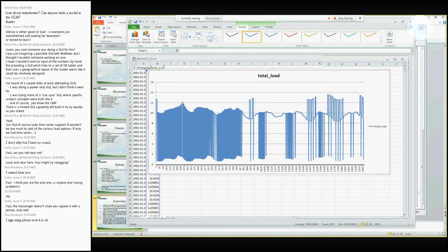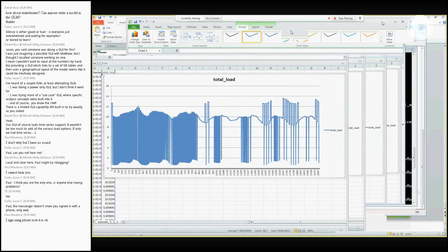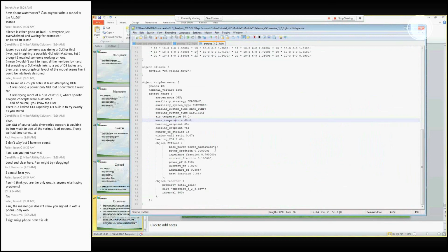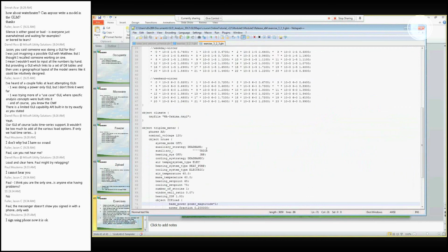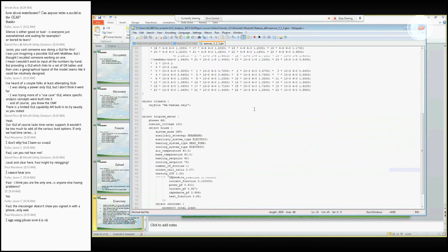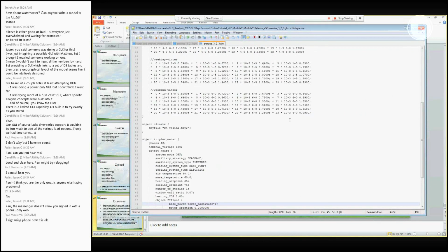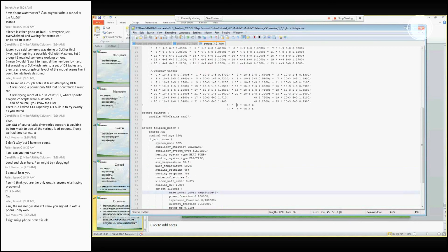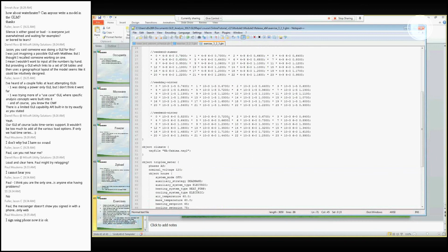What we really want to show is how we set that up. So, for example, here we set up our normal house system, but in this zip load, we created a base power, and it took these values right here and multiplied them by 1. So that should give us a base load of effectively this load shape times kilowatts. So we should get a peak load somewhere in the neighborhood of 1.2 kilowatts, except for when the HVAC system is on, of course. And then we're going to drop back down to much lower values.